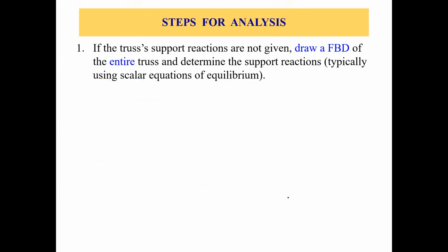Now, what are the steps for analysis, right? If the truss support reactions are not given, draw a free body diagram of the entire truss and determine the support reactions using scalar equations of equilibrium, right? So if there are no support reactions, then we need to find the support reactions, right?